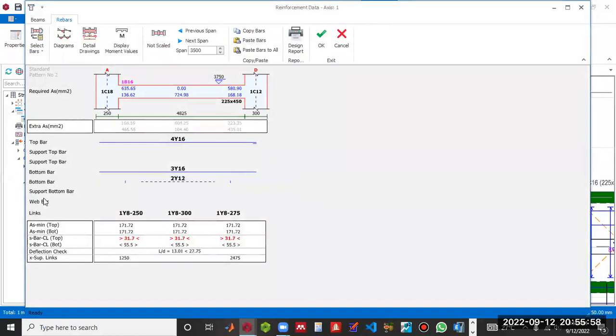But when you check here, you will see some red messages, some red issues where it is happening on the structure, remember. You will see the shear reinforcement at the support, and here also at the support, here at the middle of the span. Here it is at 1/3 of the support, here also at 1/3 of the support from the right-hand side, here from the left-hand side. You can also visualize the detailing of such structure from the detailing part of the software.